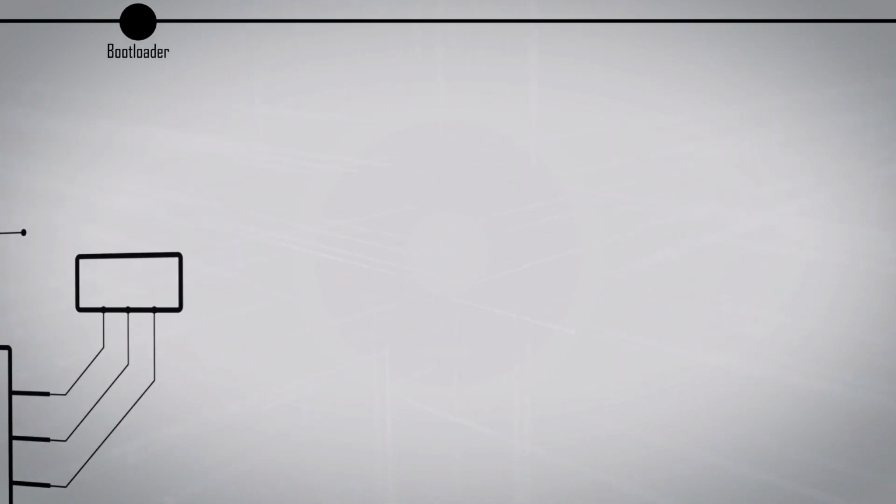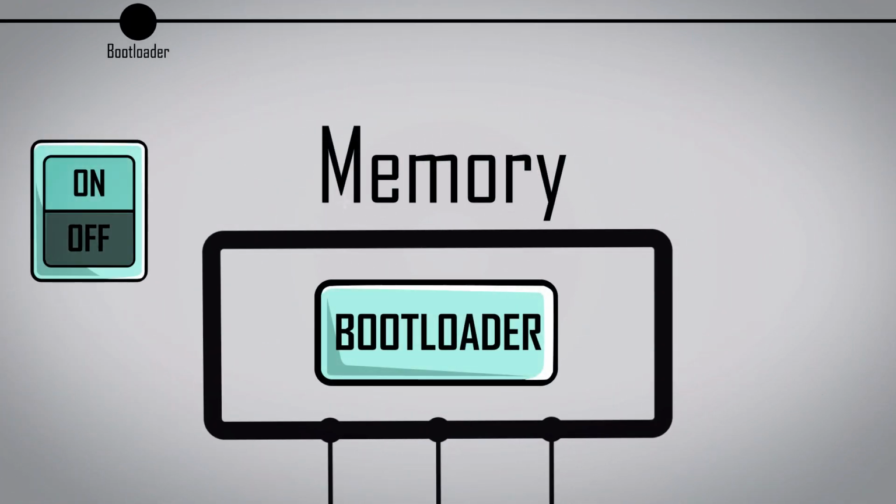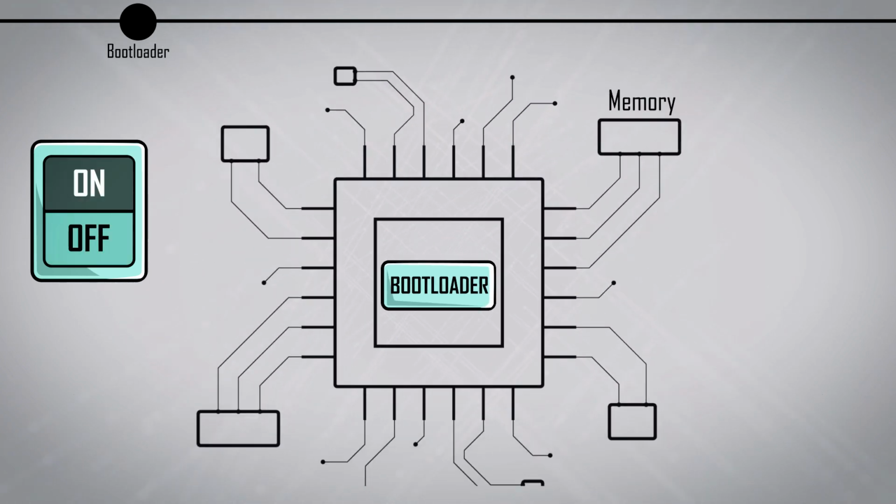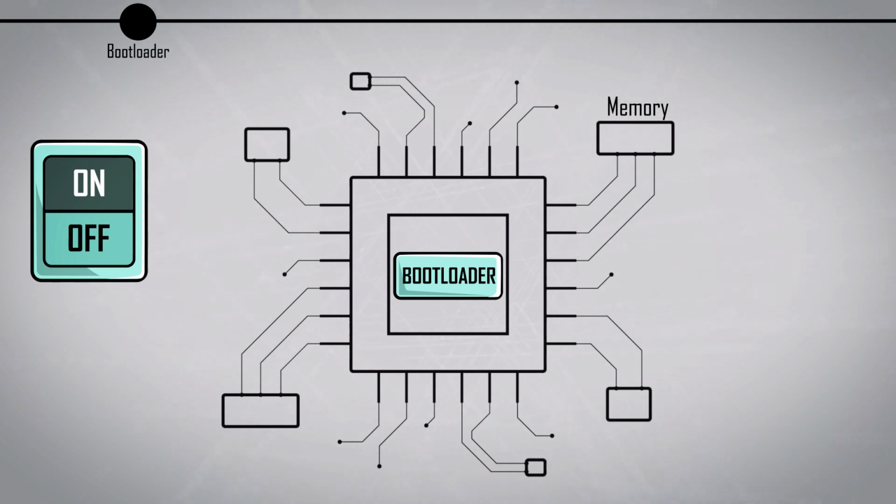Without getting into the gory details, the bootloader is a program that gets handed over to the CPU as soon as you turn on the board. This bootloader can either come from memory located on the board, or can even be transferred over some external interface like USB or Ethernet. It's responsible for helping initialize some of the necessary hardware components on the board for the rest of the OS components to run.